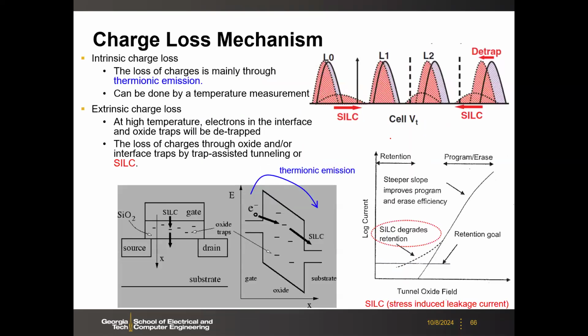So here, if you look at the distribution shift, then you will notice there will be this kind of general trend for the multi-level cell, let's say MLC. So initially, you may have this distribution, but after the baking, and then you remeasure the distribution, you will see a shift from the array. So here, let's understand what happens.